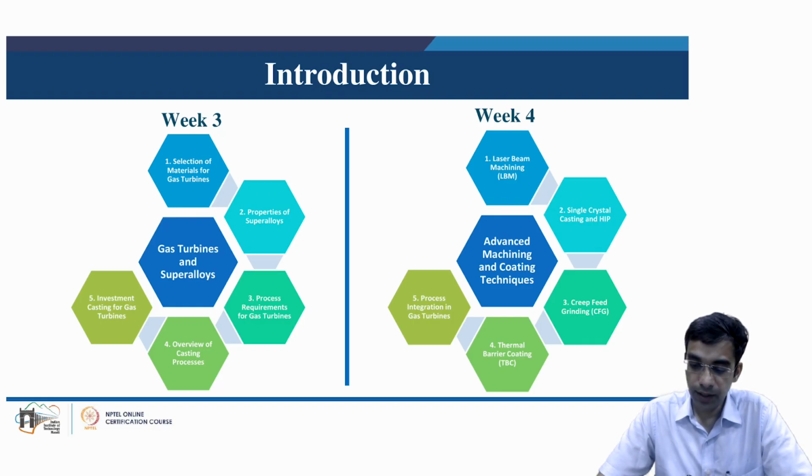In week 4, we will look at advanced machining and coating techniques which are used in manufacturing of gas turbines. In this module, we will look at laser beam machining, single crystal casting, hot isostatic pressing. Subsequently, we look at creep feed grinding, thermal barrier coating, and process integration with gas turbines.